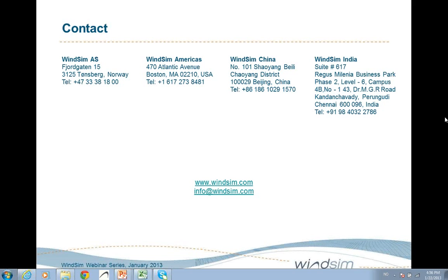The next question is, what turbulence model does WindSim use? WindSim has several turbulence models. The standard is the K-epsilon model, but in the last years we have also implemented the K-omega model from Wilcox.